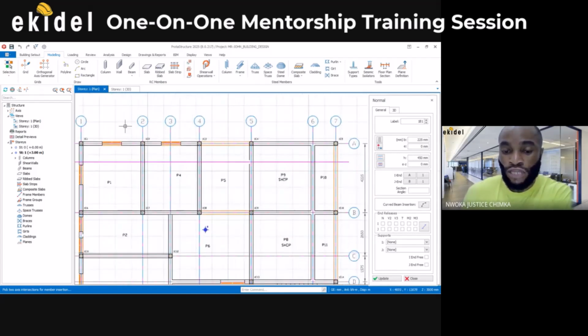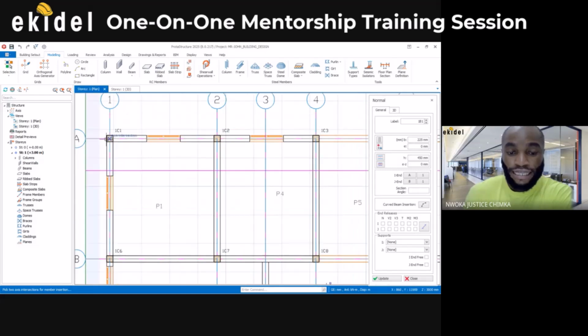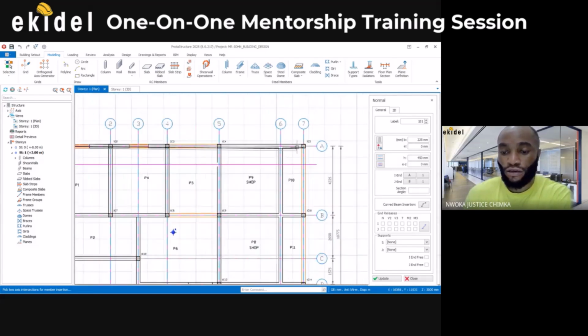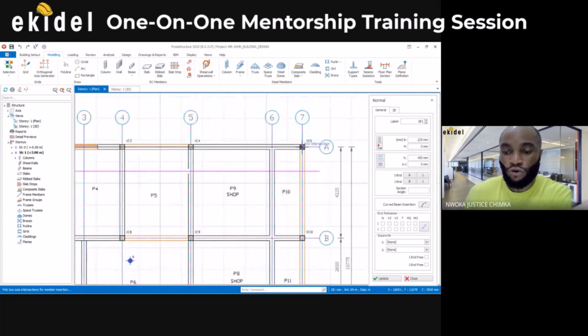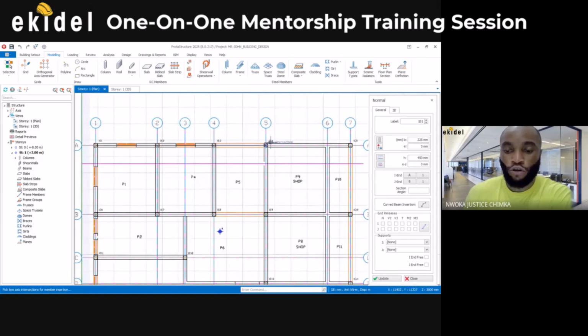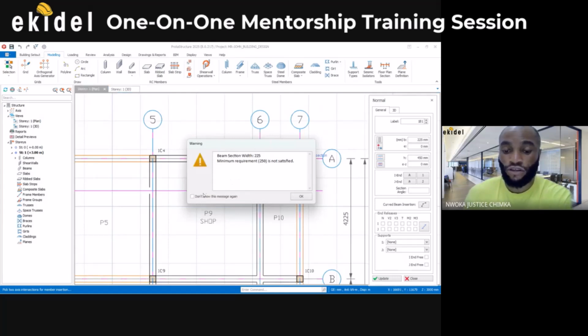So on that now, I'll click on the first column point here. Since we have our beam running from this column here to the last column here, I'll just click on the last column and then it will insert the beams, dividing it based on the column points. So I'll come here and click at this one. Then I'll hold on for a while for it to insert that. Now you can see the warning in here. Just say don't show again, ignore it. It's not that the beam section width is too small, but leave it.